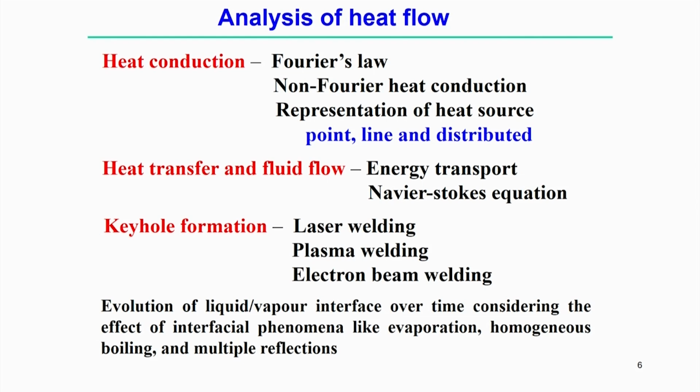Over time, taking into account the effect of interfacial phenomena like evaporation, boiling and multiple reflection, we can develop the geometrical model of the keyhole. That means we can predict the size of the keyhole in the laser welding process. Otherwise, apart from the keyhole, if there is a conduction mode laser welding process, only the heat conduction equation or maybe the heat transfer and fluid flow equation is sufficient to predict the temperature distribution.